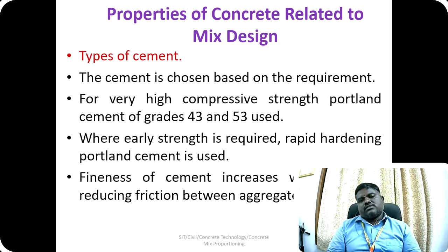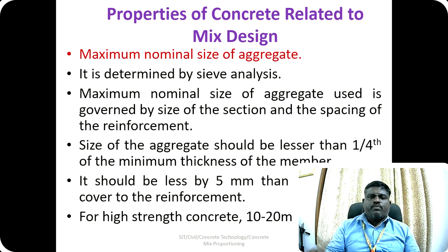The fineness of the cement will increase the workability by reducing the friction between the aggregates. So based on the fineness also, the mix design is going to be affected. The third property is the maximum nominal size of the aggregate.